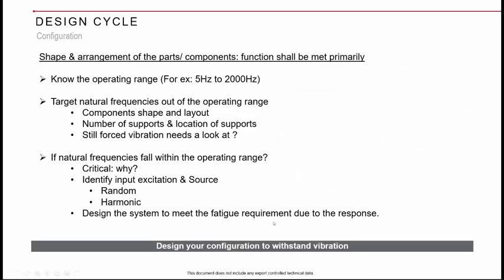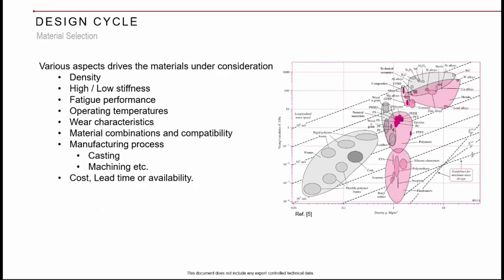Okay. So that is one aspect, and the frequency is another aspect. So what you should do, consider as a part of material selection, you should have low density. So density should be one criteria for you. Lesser the density, higher the frequency will be, square root of k by m, if you see the natural frequency expression.